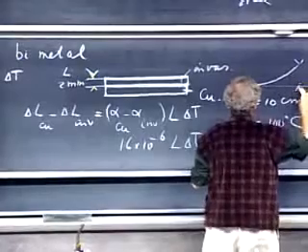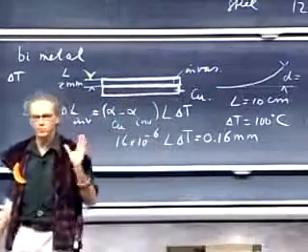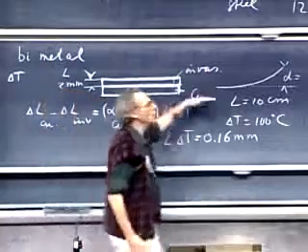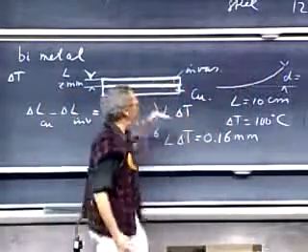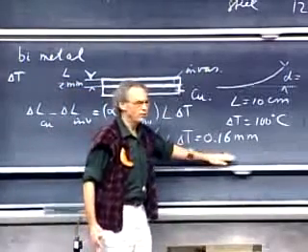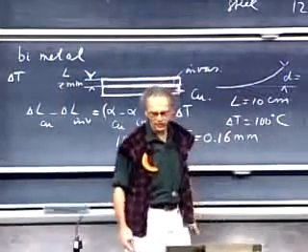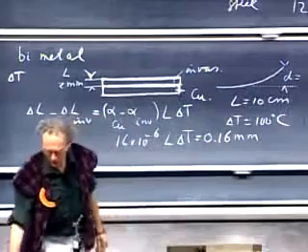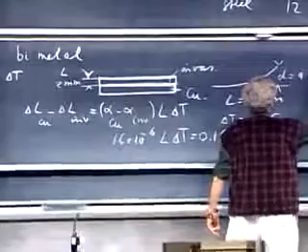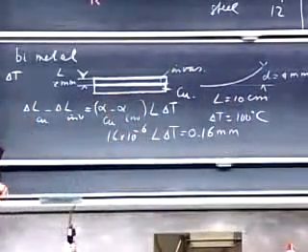And yet, this one will curve substantially. For those of you who are mathematically oriented, I would advise you to make an attempt to calculate that. So you assume that it is a perfect circle. That's a reasonable approximation. And so you have an outer circle, which is longer by 0.16 millimeters than the inner one. And you try to solve and find what that d is. And I went through that exercise, and you want to do that too, perhaps, and I found that it's 4 millimeters for these dimensions. 4 millimeters. That's substantial.